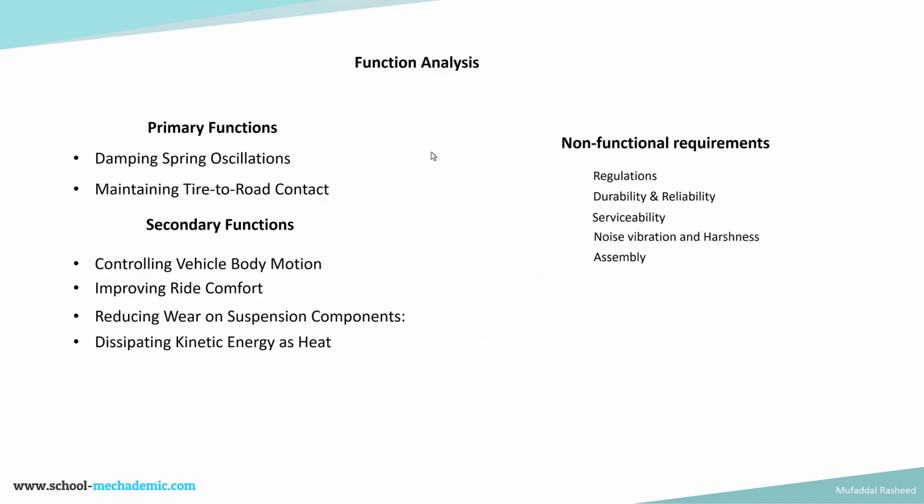The next step is to perform the function analysis, in which we are investigating and listing down the primary and secondary functions of the system, and also the non-functional requirements of the system, which are not related to any function, but they are required as a part of any mechanical design consideration. So primary function, the first is damping oscillations. That's the most primary function of a shock absorber.